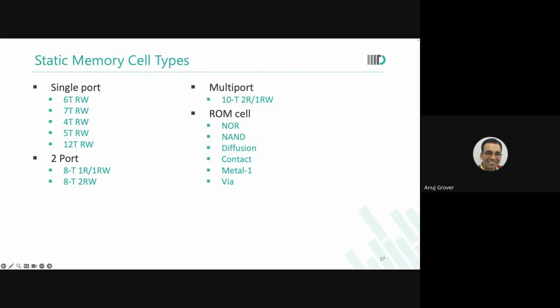So the pure dual port memories are typically used when you have the same data which you want to keep alive and used by two processors simultaneously. One processor will access from here, the other processor will access from there. And you remember we talked about the priority thing there, that my state machine could have an arbitration engine in it which says, okay, port A gets higher priority over port B at all times when there's a write happening.